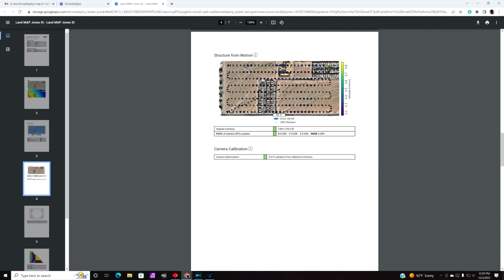And there's another way. I've done this so much that I'm confident in these numbers, but if you need proof of concept, I can lay down checkpoints in the map and record those checkpoints with the GNSS receiver and compare those checkpoints to our accuracy shown here, and it will validate the accuracy of the map. I didn't do that today, as I didn't need to, because I've already worked for this client before. They already know that everything's accurate, but if needed, that can be done just to validate the accuracy of the map. No issue whatsoever.